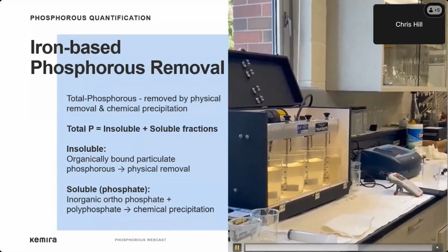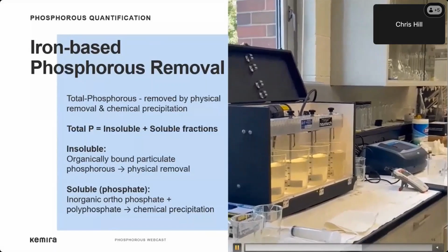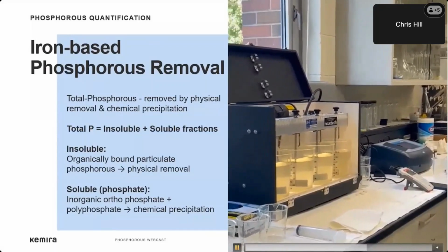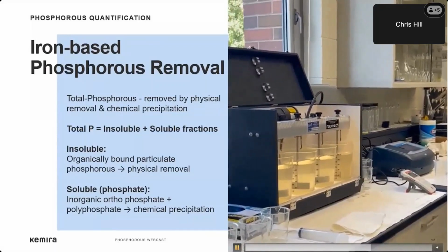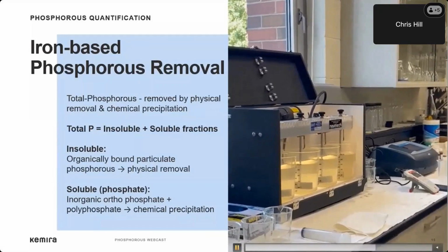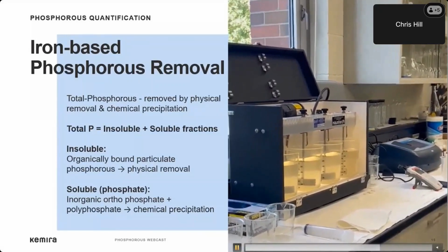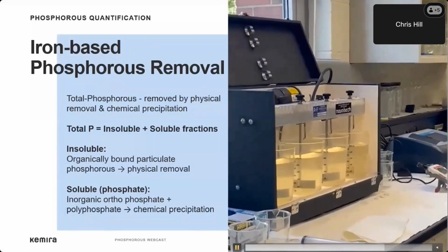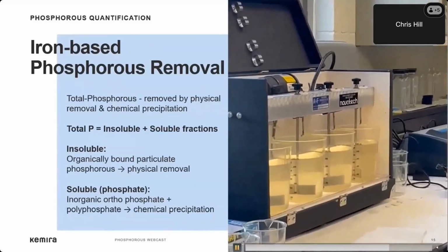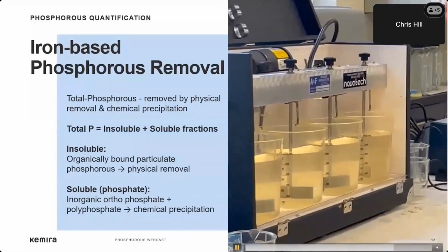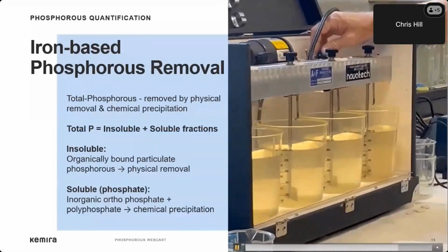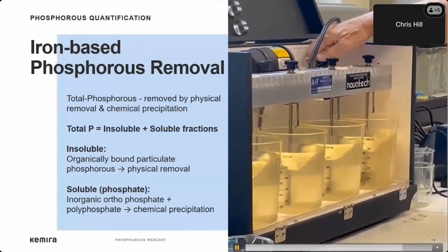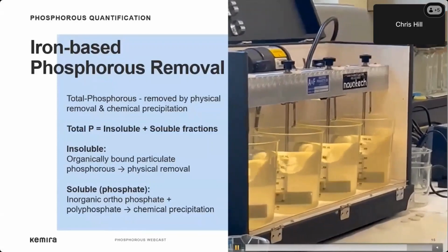Metal hydroxide forms and creates a gelatinous floc that aids in binding the iron phosphates and the suspended solids, including organically bound particulate phosphorus. The wastewater contaminants become entangled in the hydroxides, causing most remaining contaminants to be swept down with the settling hydroxides. This process is known as sweep coagulation.